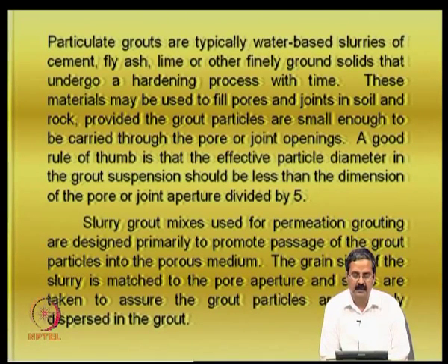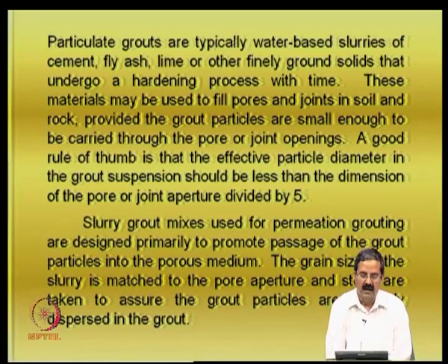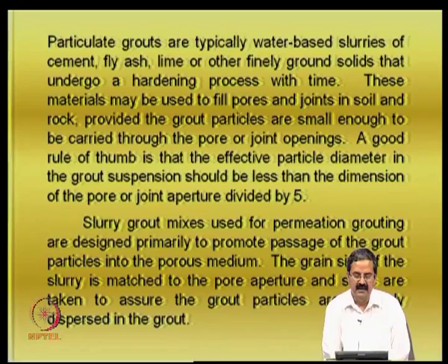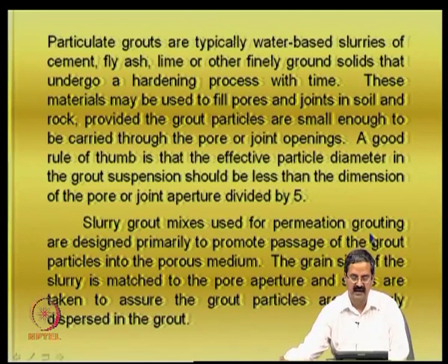because many of these materials, like cement, have a time-dependent response, and they have a pozzolanic action as we discussed earlier. These materials can fill up pores, but as we also discussed, if the pore size is going to be smaller, then it is not going to be effective.